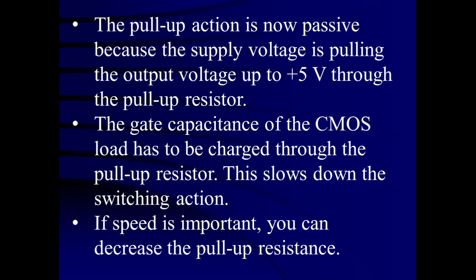How much can this value of the resistance R be reduced? Who puts the limitation over this value of R? That is, when the output of the TTL is going to be low, then the lower transistor is conducting and the current is sinking through that transistor because the lower leg of the resistance is going to be at zero potential.